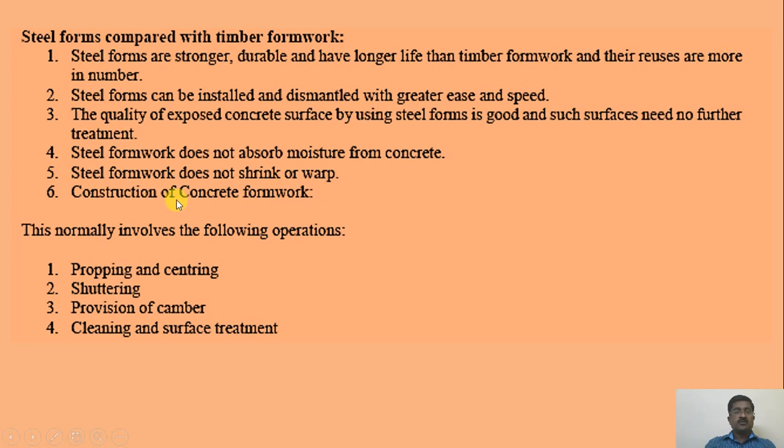Construction of concrete formwork normally involves the following operations in the shuttering process: propping and centering, shuttering, provision of camber, that is the slope required, cleaning and surface treatment. Thereafter it will become ready for placing the concrete.